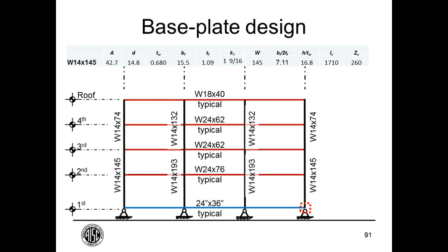All right, we're going to stay right here for the next question, a related question actually. Is it acceptable to assume a fully fixed or perfectly pinned base of the column in an analysis? So it is, according to AISC 360, if you have a pin assumption in a connection, you have to be able to accommodate the rotation involved.